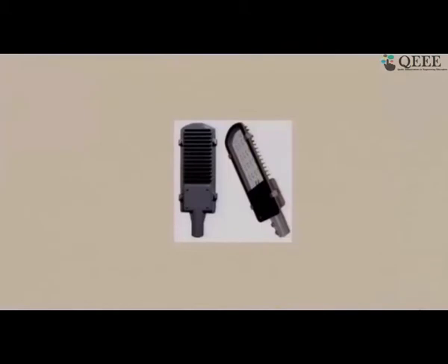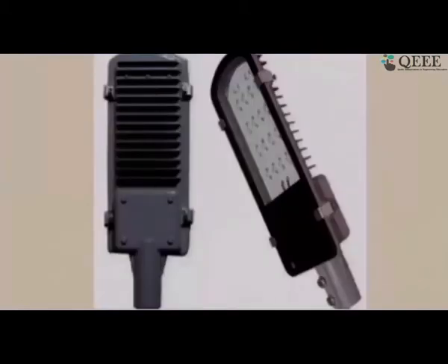This is another example, and we are seeing a lot of these LED lights these days, and the same issue: that LEDs are generating heat on this side, and on the back, as you can see, this funny looking thing is a heat sink to transport the heat away and keep the electronics in the plate inside within a certain temperature. And this has to be out there in the open, so it gets all types of things that the climate can throw at it. It will get rain, it has to withstand storms, there will be dust on it, there will be birds sitting on it, everything is going to happen on this.